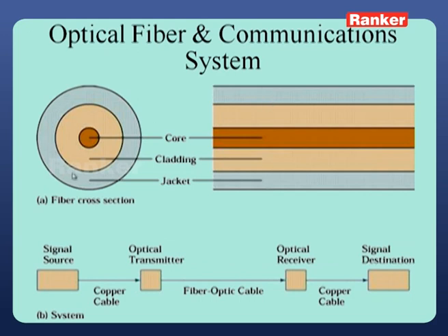And the top one is this one. This is a material made up of some plastic which will be used as a jacket for this core and clad, which is used to protect our optical fiber cable. The optical fiber cable is very, very narrow, very, very thin in its dimensions, sometimes of the order of micrometers, so it will be very delicate. This jacket is used to provide protection to that particular structure. So this is our optical fiber cross sectional view.